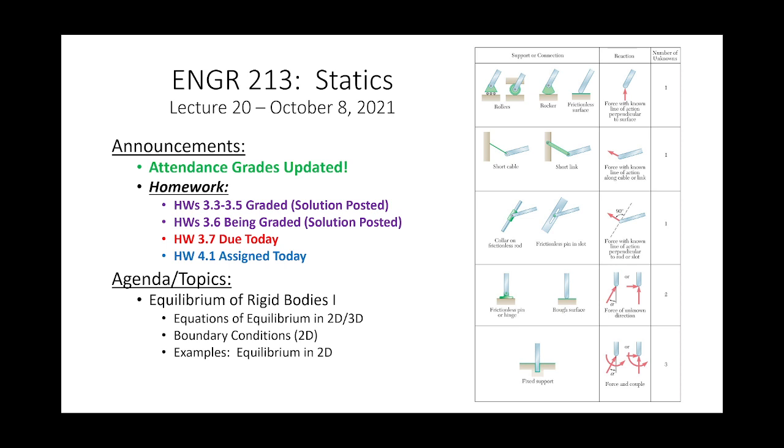So in particle statics, we did all this in that second module. The first thing that we did is we just learned how to add vectors. And then the second step was, if I have a point subjected to a series of forces, what are the external unknown forces required to keep that particle in equilibrium? The balloon problem is a perfect example of that. We had a particle that had a force applied to it. The balloon was yanking it up, right? And so what were the tensile forces in the three cables required to keep the particle in equilibrium? That was a static equilibrium problem for a particle.